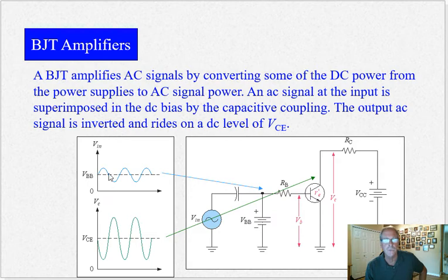So there's an inverse relationship between the voltages between the base and the collector. So higher base voltage, higher base current results in a lower collector voltage, but a higher collector current. So you're basically turning this transistor on a little bit or off a little bit with your base current.